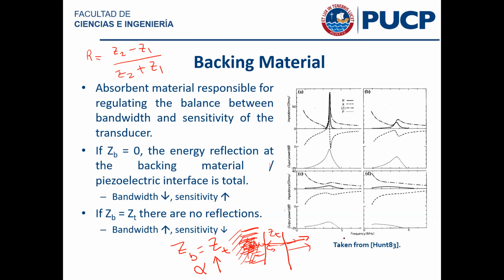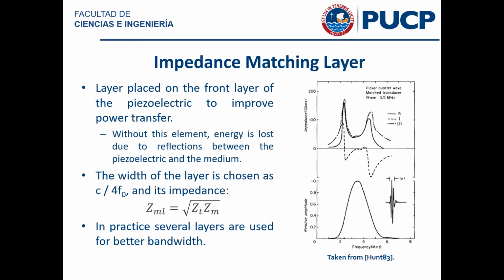So in practice, what you want is a little bit of the two. You would design your backing material such that you have a reasonable bandwidth and a reasonable amount of energy produced by the piezoelectric, or the transducer, I guess we can say safely in this case, because we're actually building a compound on top of the piezoelectric element. Okay, so that's one of the things that needs to happen in here. The other element was the impedance matching layer.